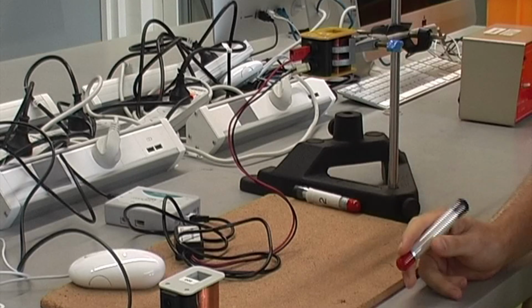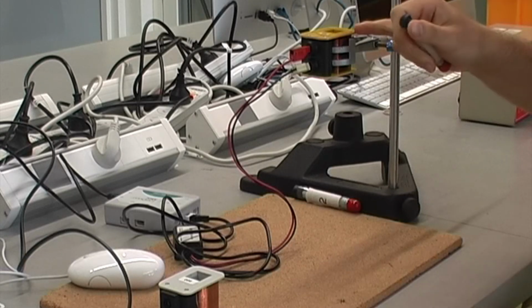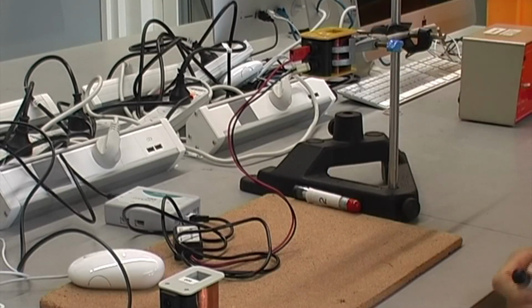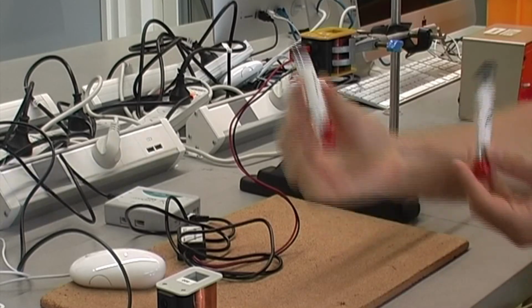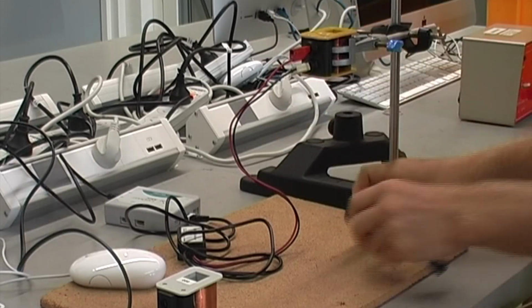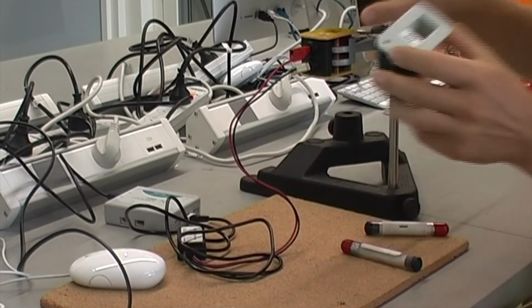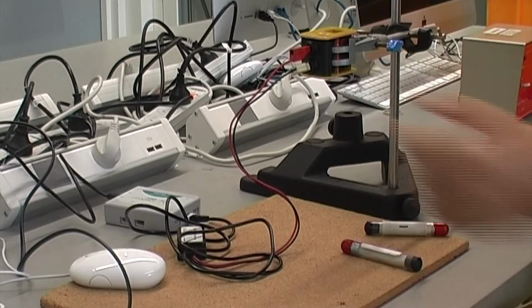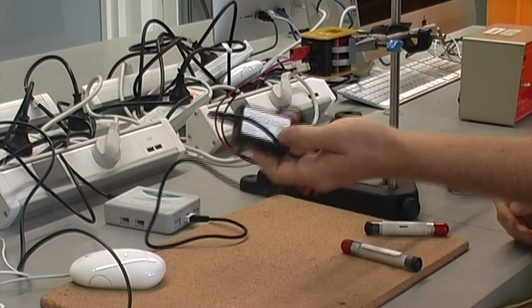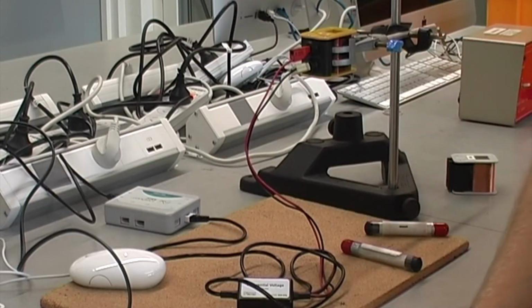Okay, so this lab's based on Faraday's law, which means if you pass a moving magnetic field through a coil, then you can induce an EMF. So that's what we're going to test with the first part of this experiment. So what you'll need is your two different magnets, which are placed inside these tubes, and they've got black and red to denote the poles. You've got your two coils, so the only difference between these two is just the amount of turns in each coil. And we've also got this differential voltage meter which plugs in and goes into the LabQuest to give us a reading on the computer.